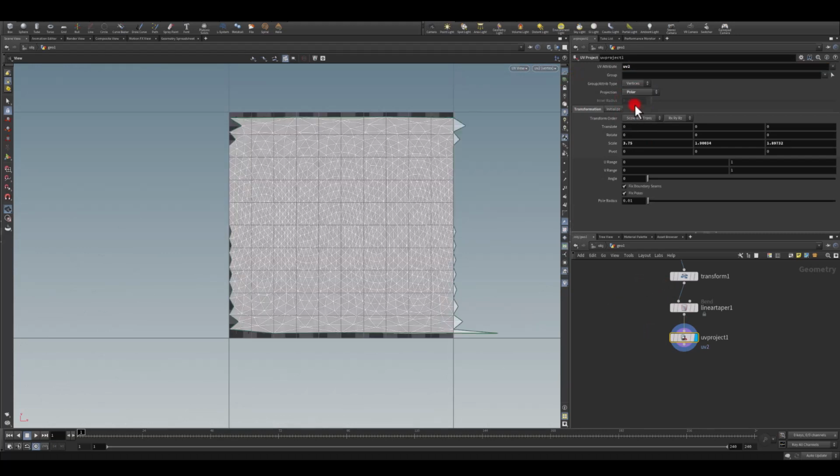And in here, I'm gonna change this to be a polar projection. And as you can see, I don't have to do anything. Just gonna press initialize. If you see something different here, you can try different planes and see which one works best for you. And once you change the plane, just click initialize. But I think the default option should work for you as well.